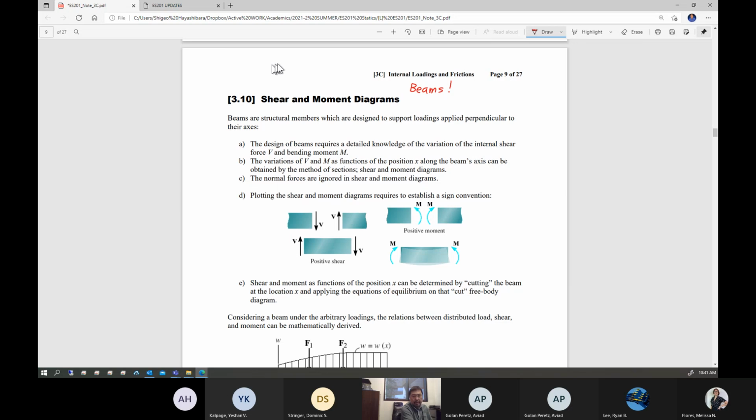Now, as you saw in some of the example problems, beams are the typical structure, designed to take either perpendicular loading or moments. So this is the typical beam, okay? It is pinned-supported and roller at the other end, so it introduces 3 support unknown reactions. And then you can apply a variety of things to this kind of structure.